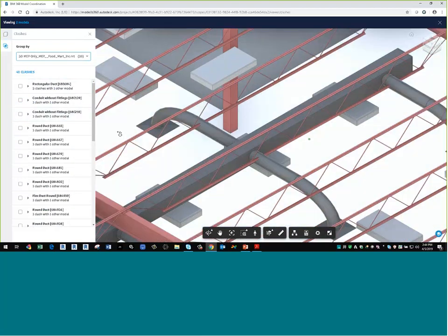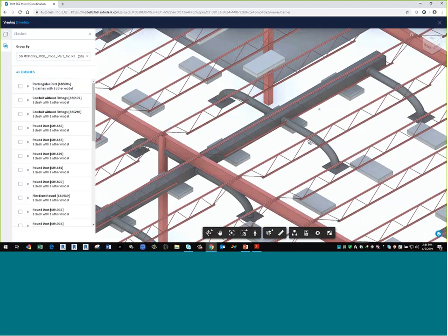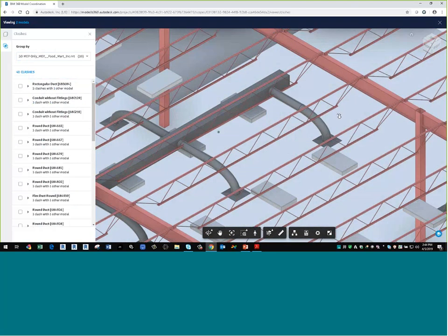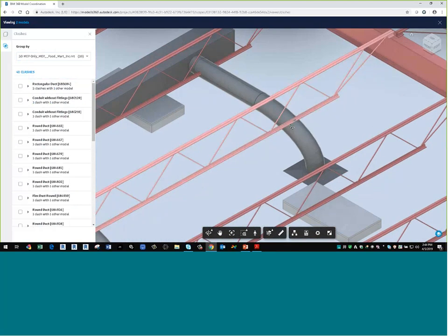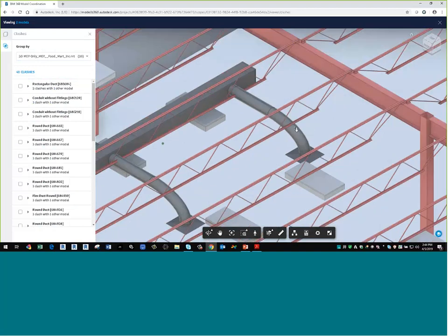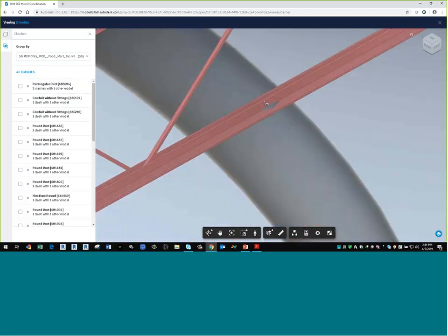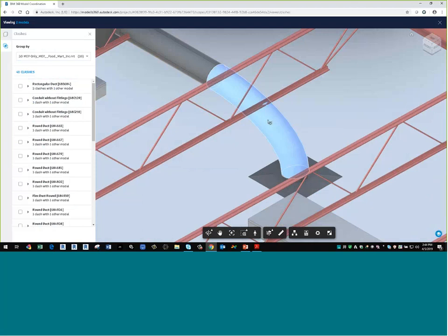Now maybe you run into something that, well, it's supposed to do that, or it's a flexible duct right here, right? So that's not really a clash, right? It's flexible duct. I just go around it, easy enough, right? So it's a tiny, tiny clash. You can see it there. So you could actually come in here and say with that object there that that's not a clash.